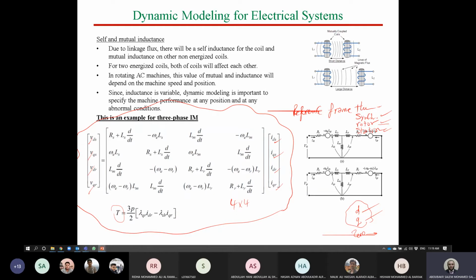You cannot make calculations to get which value of voltage should be applied now in order to get that speed. You have to make something adaptive. Something adaptive means closed loop control. In order to make closed loop control, you need to add something called a controller or compensator, like a PI controller, for instance.